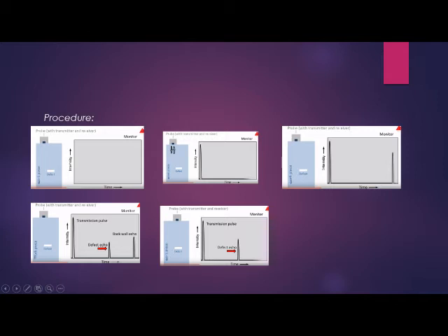in the same way, you have intensity at first. After that, the wave touches the defect area first, so in the monitor there is a defect echo, and then after that the backward echo. And then if the wave touches the defect, as you can see, the defect echo will show.